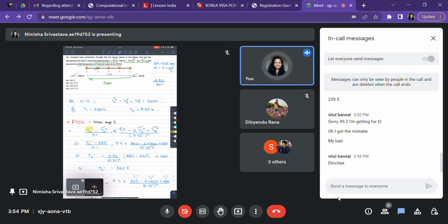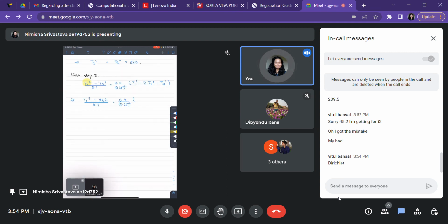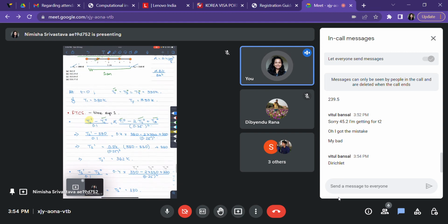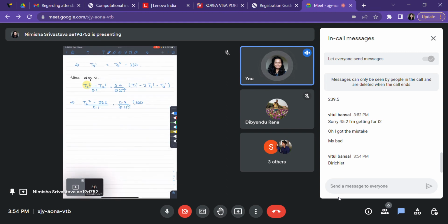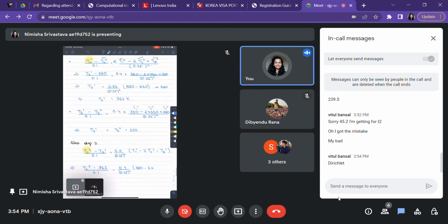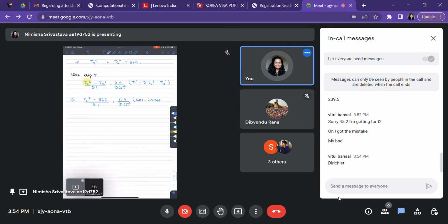Great, Dirichlet. Thank you. That's a Dirichlet boundary condition because we are imposing the temperature, that is, we are imposing the function at the boundary. Okay. So then T11 is equal to T10 and it's a time invariant boundary condition. Then we have 380 minus 2 into T21, 362 Kelvin, minus T31. So what is T31? T31 was 330 as we had computed earlier.